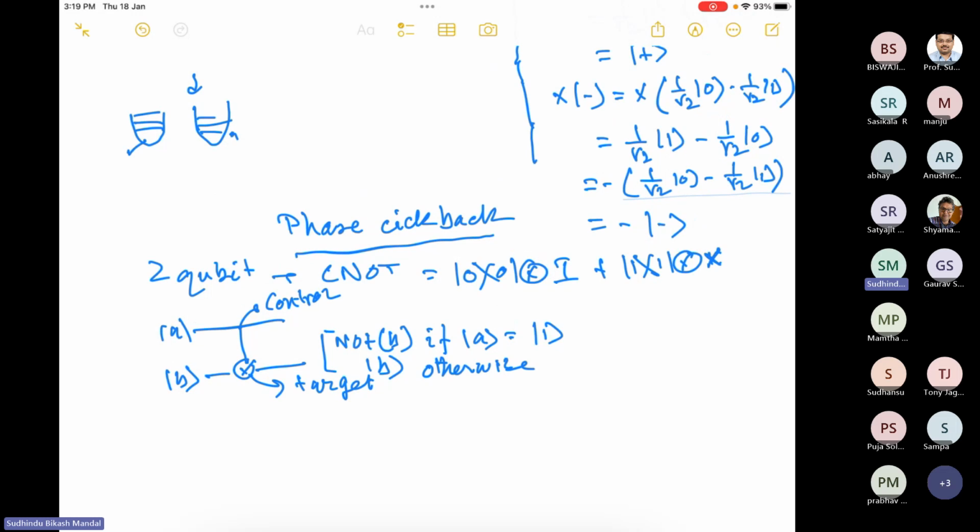So why does this CNOT gate give more error? Because we need to couple this to the anharmonic oscillator as well as to the cavity or resonator. So there are so many interactions between the fridge where the qubit is, and outside of the fridge there is some other toolbox. We need to interact more. That's why some environmental interaction is coming. So designing a pure 2-qubit gate is still challenging.